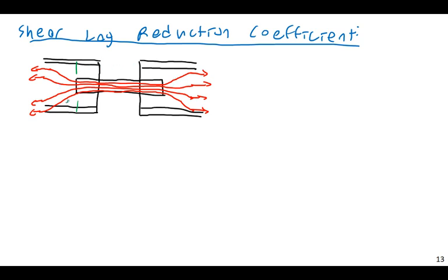So the critical cross section for fracture for the wide flange shape really isn't way over here. Way over here, yes, the entire cross section can carry tensile load, but here it has to bunch up, it has to concentrate. So this is stress concentrations. And this really is what the U factor, the shear lag reduction factor, takes into account.